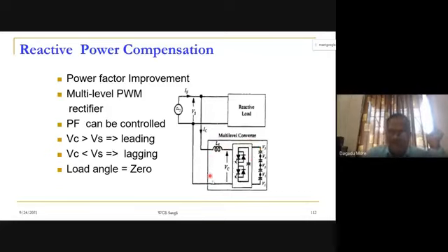No doubt, sir. Okay, then let us go for the last bit of this, that is the back-to-back intertie. You have a full subject on HVDC, is it right? Yes, sir. So what pulse number do we use for HVDC? Which devices do we use in the converter and inverter of HVDC? GTOs or thyristors? Okay, we are using thyristors, and the normal configuration is a 12-pulse rectifier and 12-pulse inverter.